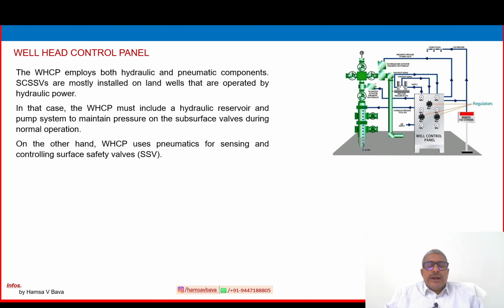On the other hand, the wellhead control panel uses pneumatics for sensing and controlling the surface safety valve. So the subsurface system mainly uses a hydraulic system, and the surface system uses a pneumatic system, with compressed air or available instrument gas.